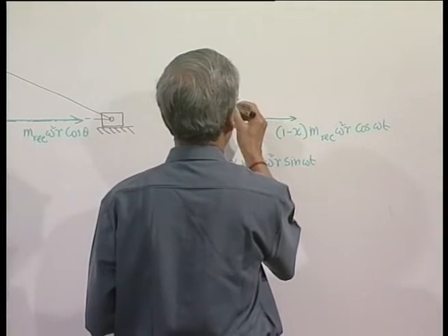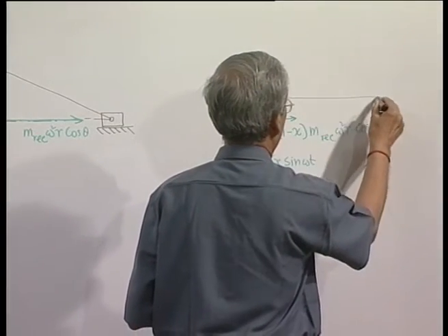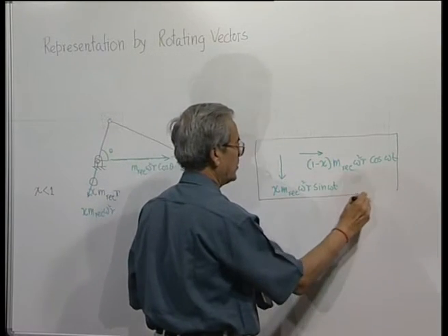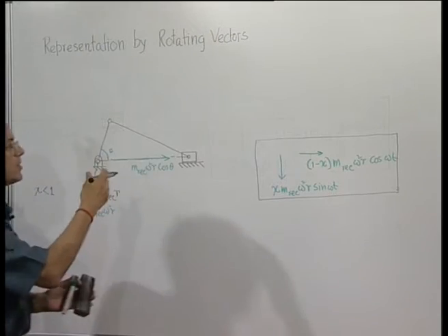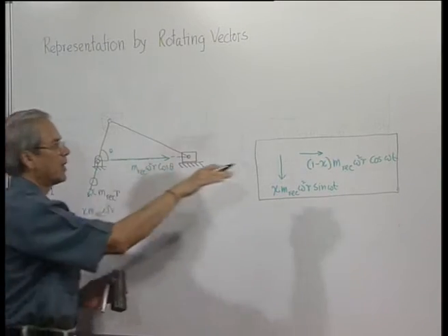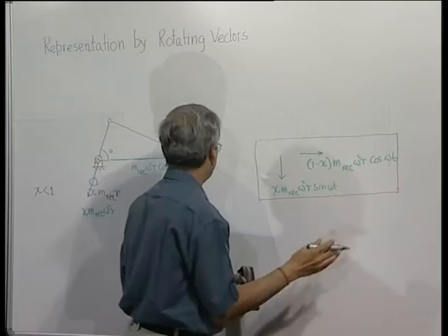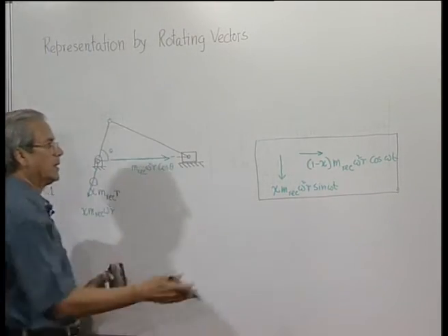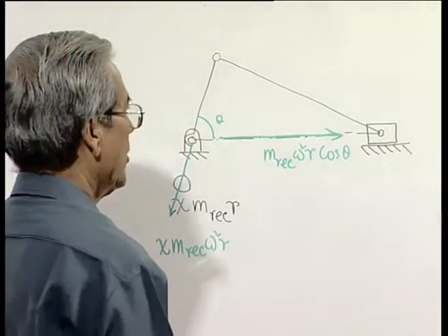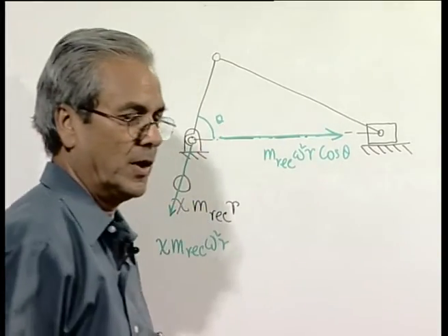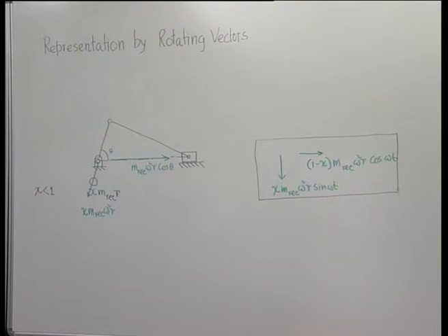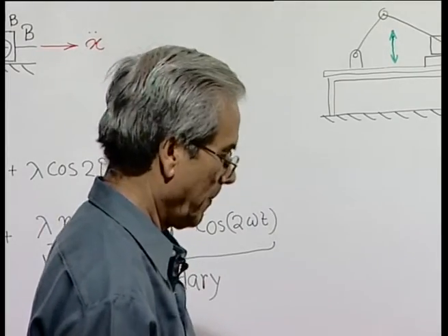So the engine, if we represent it by this outline, the unbalanced force in the engine in the x direction is this much, which is obviously less than this, but we have also produced another unbalanced force in the y direction, which is also less than this in magnitude. So, sometimes this partial balancing is adopted to reduce the amplitude of the oscillating unbalanced forces.